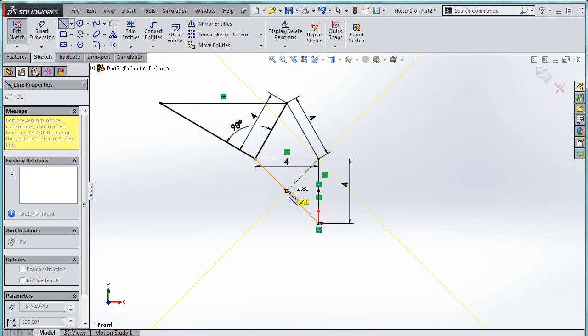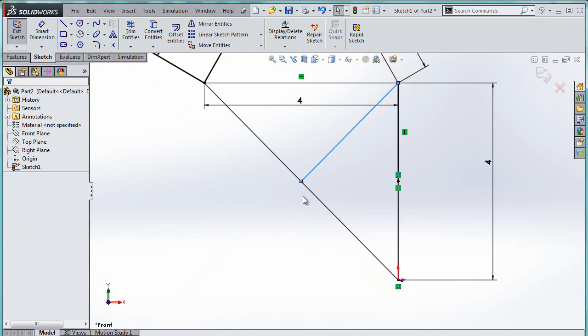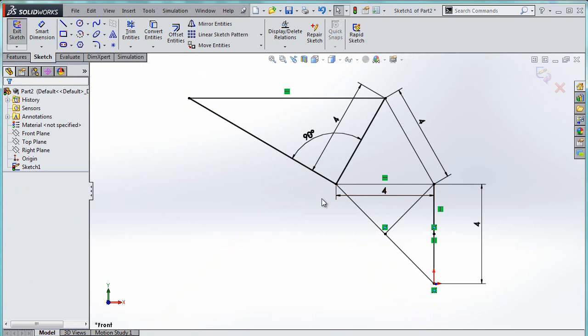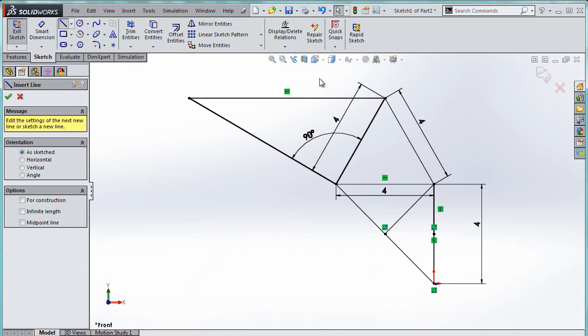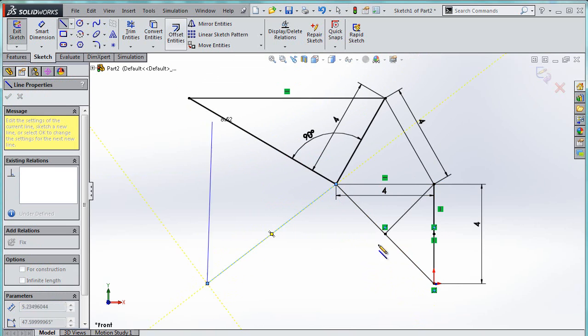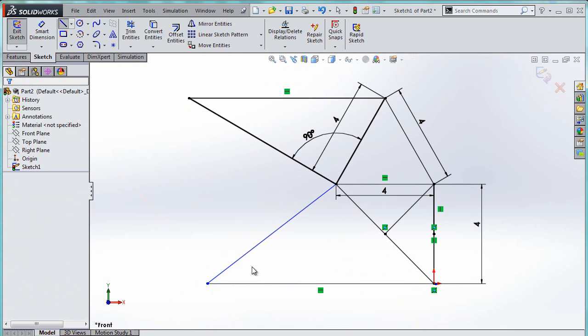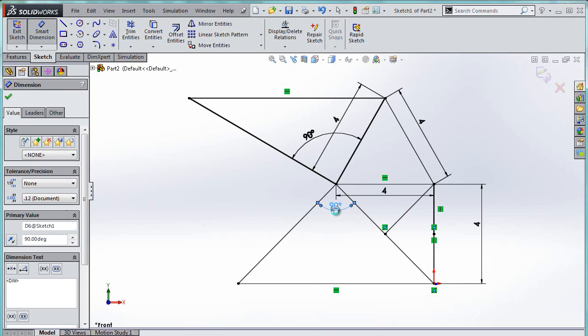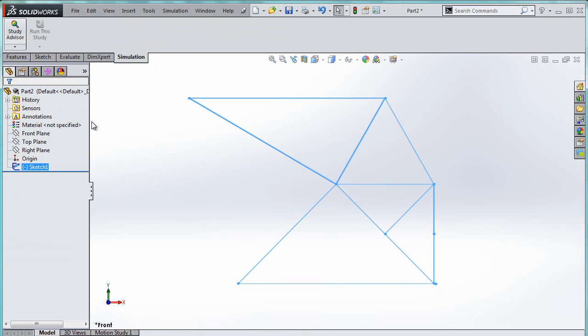And you see there's that little yellow sign that's like the coincident and the perpendicular. Whenever I click on that, it's still blue, so I'm going to zoom in. I don't know why it does this. If I pick it up, it lets me move it around, but whenever I take it exactly back to where it was, it's like, oh, that's what you meant. It's fixed now, so that's good. Then we have a line going from here to here, and a line going from here to here, and we care that this angle right here is 90 degrees. Beautiful. So I can exit this sketch.